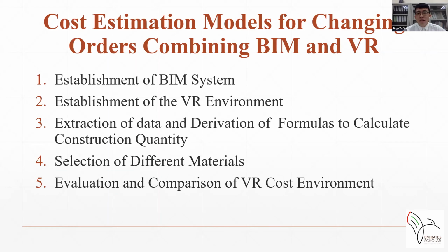The second is establishment of the VR environment. The importation of a BIM system into the game engine in an FBX file format results in loss of render data. Therefore, the system must be re-rendered in the Unity game engine. Additionally, a BIM system does not include interior lighting. Hence, skylights must be added manually with Unity before the light mapping calculations. The third is extraction of data and the derivation of formulas to calculate construction quantity. After the connection of the BIM database to the game engine, the program can extract data from the database and add formulas for quantity calculation.